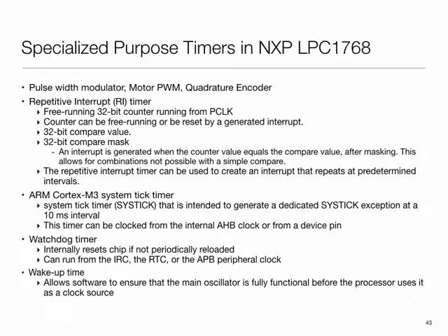But the other thing is that the level of precision has improved tremendously, because while in principle you could do PWM generation and time stamping of events in software, you would take a huge performance hit because of the delays involved. Whereas by creating these dedicated, almost specialized timing related processors, you take care of that.